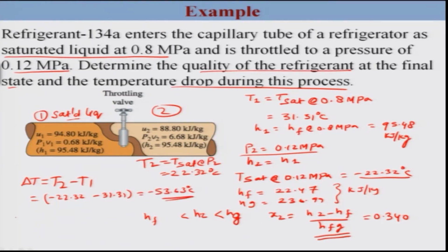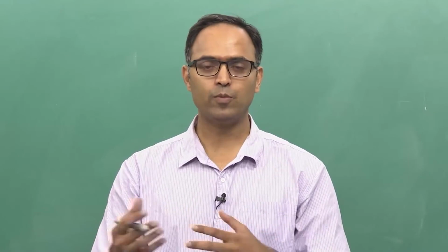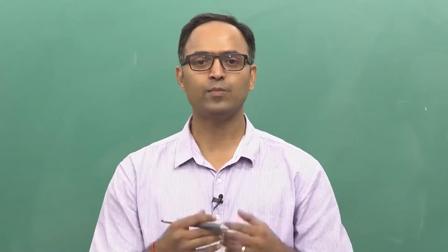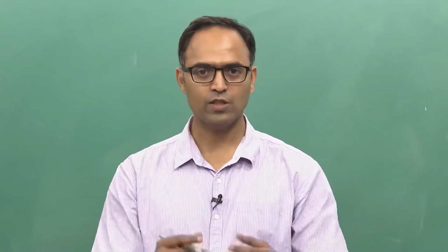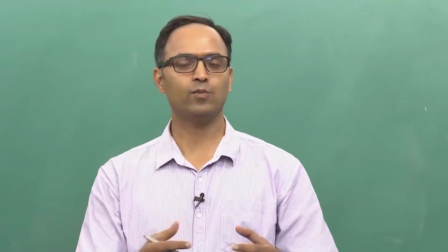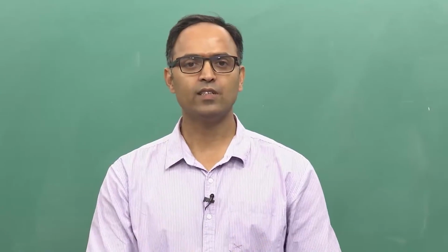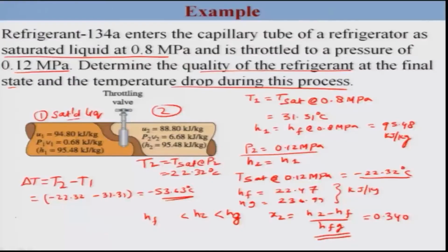So it's very clear that there is a significant drop in the temperature, and the saturated liquid vaporized. The energy to vaporize, it takes from its own enthalpy. That's something which is quite interesting, because the energy required is not taken from any specific external source, but it changes its own state through this particular capillary tube and makes use of it for vaporizing from a saturated liquid to saturated vapor liquid conditions.